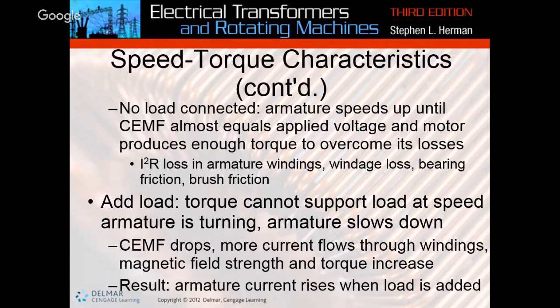As that bucket is engaging the bank, those motors are saying, okay, full speed, but the torque is like, oh, geez, I can't give you full speed. I've got this huge amount of load on. So that's when you'll see that current just go up to like 3,000 or 4,000 amps. Just skyrocket up in there to try to generate that speed to get that bucket pulled up through the bank and then hold it while it's going out to dump it in the back of the truck. So it's pretty cool stuff.